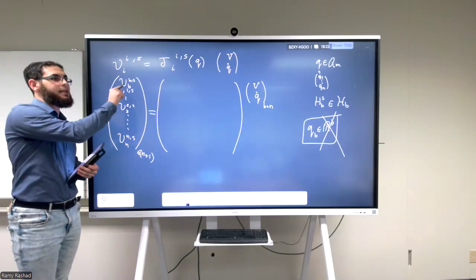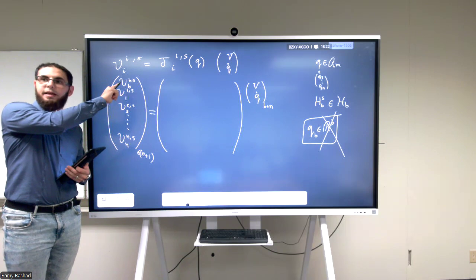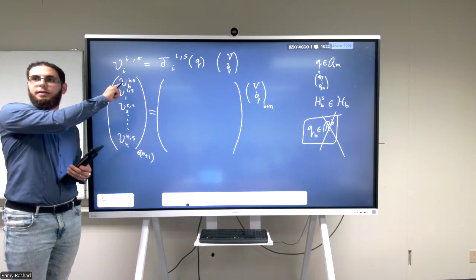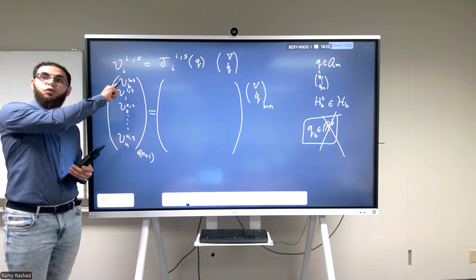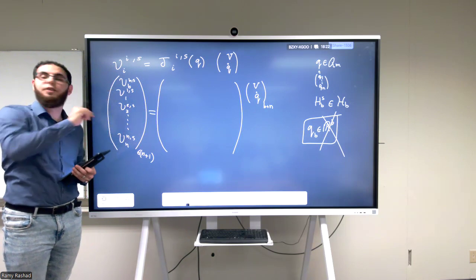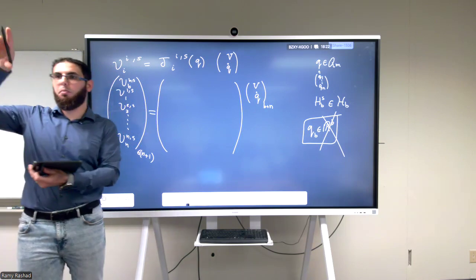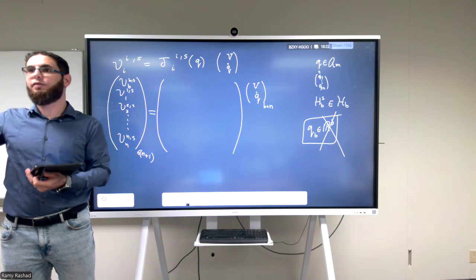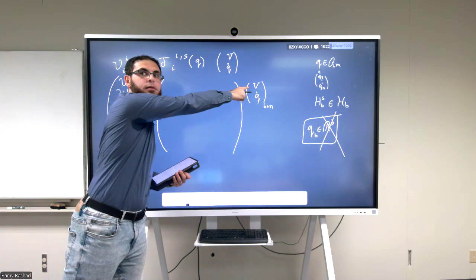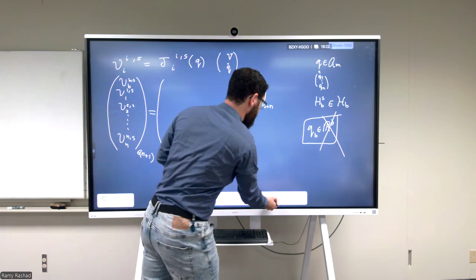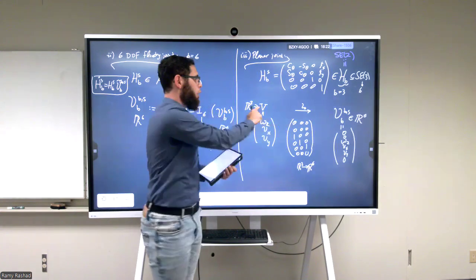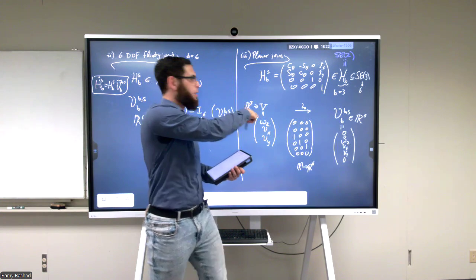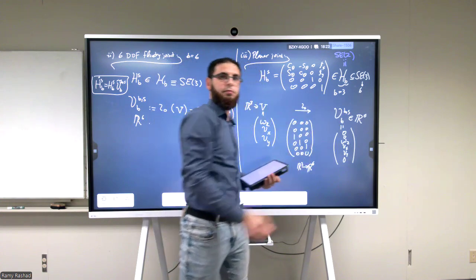No, the twist is always 6 dimensions. No matter what the base is doing, you always have a 6-dimensional twist. That's the relative twist. It is always 6 dimensions in terms of numbers. You always have 6 numbers. How many of these are zeros and how many are changing depends on the V. This is why the map iota that we introduced always maps this R^b vector to the R^6 twist.